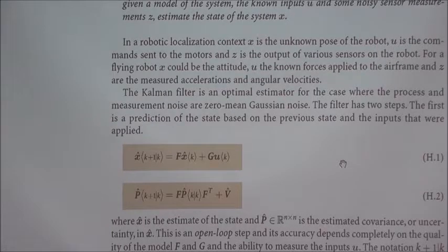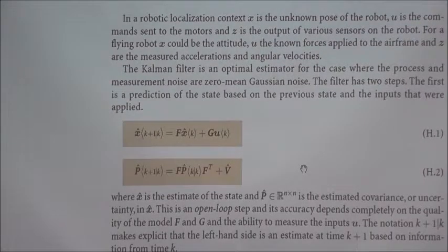However, in those early aerospace applications, like NASA's, they came up with the extended Kalman filter, meaning that you look at the pose equation of the vehicle, you linearize it with the Jacobian matrices, and you come up with an approximate linear model. Then you can use Kalman. That's what's called the extended Kalman filter, and it is a part of your robotics toolbox.